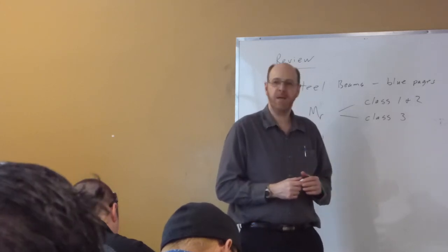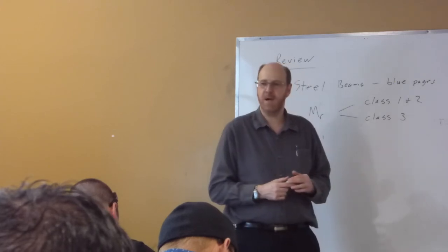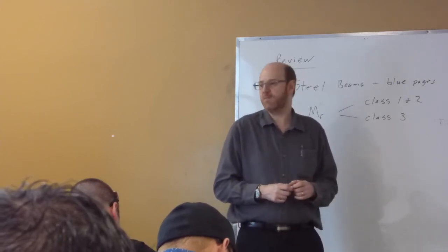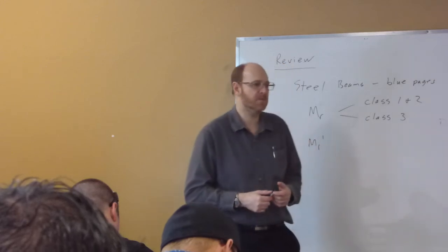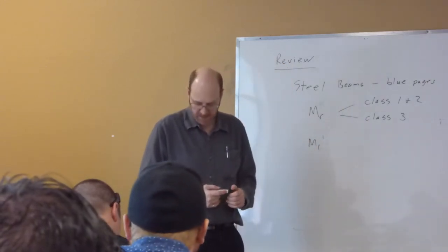So the big part is calculating where the location of the neutral axis is and calculating our moment resistance of that plastic state from first principles. So force times distance plus force times distance. So it's a little bit time consuming, but it does give us an advantage.